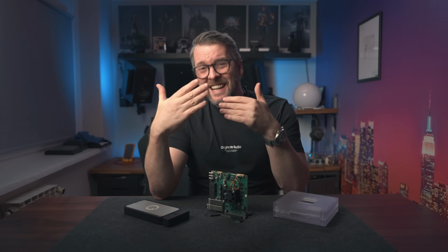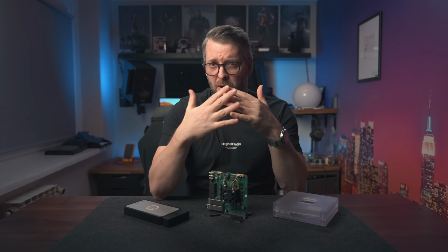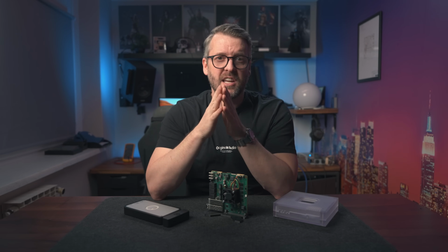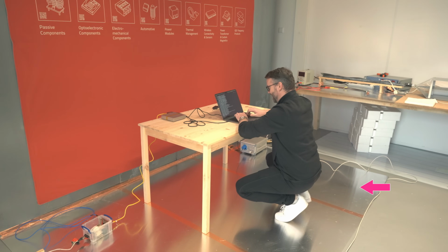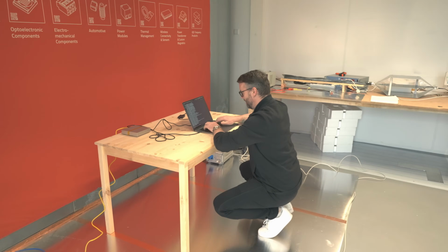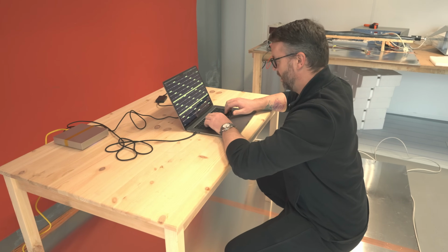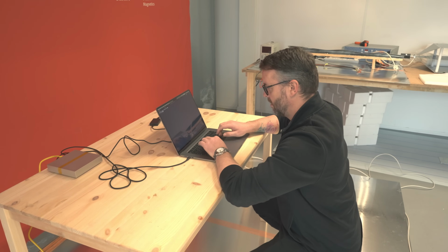While testing the radiated emissions in the anechoic chamber was definitely the focal point of the day, we were also offered to do conductive emission testing, which took place just outside the chamber on what is called the ground reference plane. You see, electronic devices don't just emit electromagnetic waves when in operation, they also disturb the mains power network when they are connected to it.